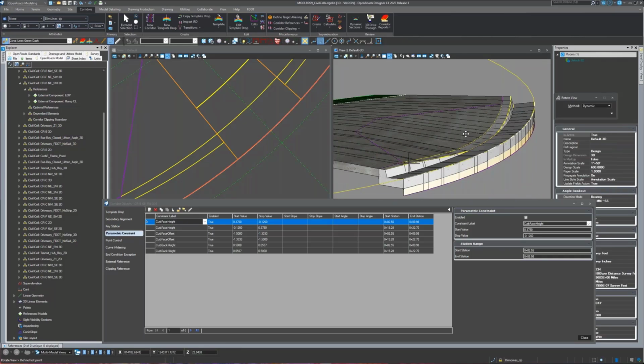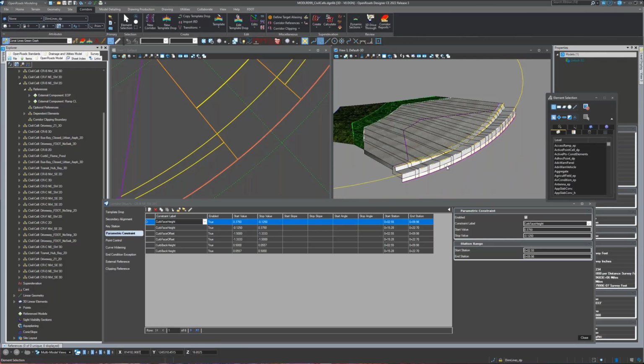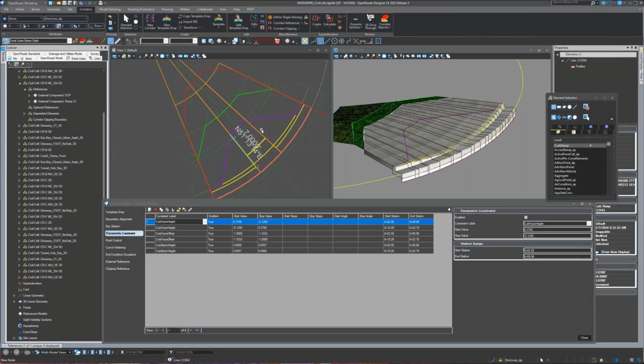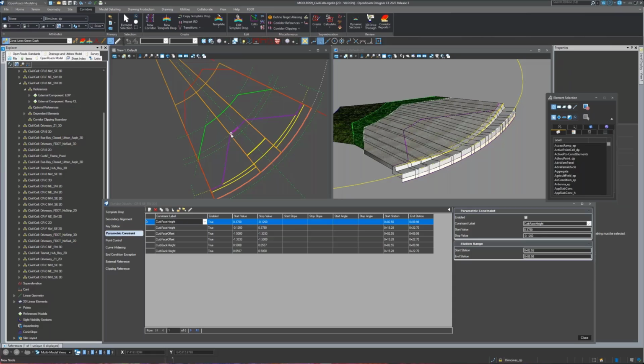One of the things that I really want to do in the future is be able to evaluate the slopes in here. I'm drawing everything as if it's just a standard curb ramp. But right now I would just need to put some profiles on a few of these things, like on that point, that line, and that line, to determine what my slope is. Is this steeper or flatter than 1/12?